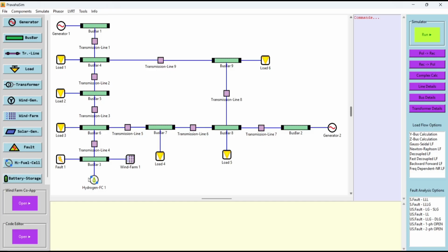But this control logic takes a little bit of time to actuate, during which the system frequency dips much higher than in conventional synchronous generator connected systems. Synchronous generators have natural inertia, which resists the rate of change of frequency (RoCoF) and resists the frequency dip, unlike in highly renewable-penetrated systems. This high frequency dip can cause grid failure or other vulnerabilities. So to resist the frequency drop, some backup system must be present to arrest the high RoCoF during this fault condition, where wind farms take time to initiate recovery. For that purpose, energy storage systems are very useful.